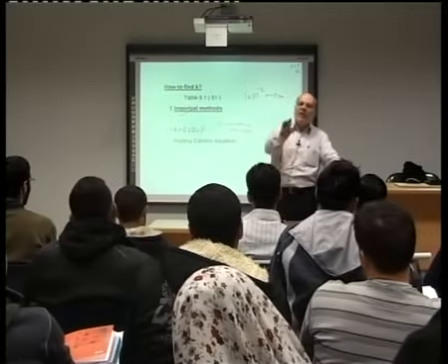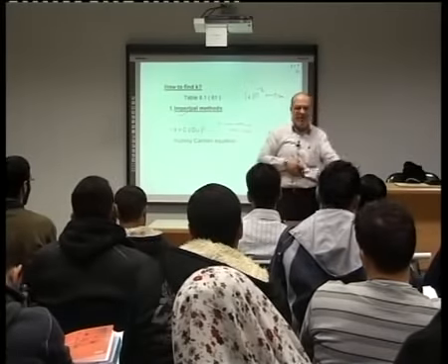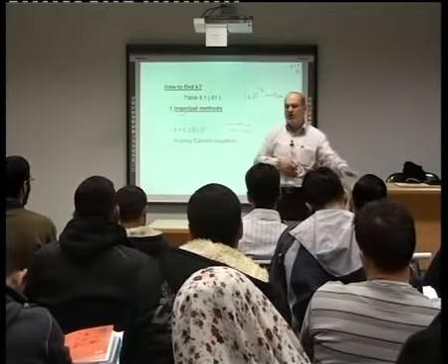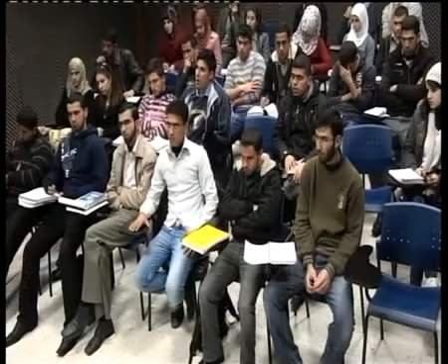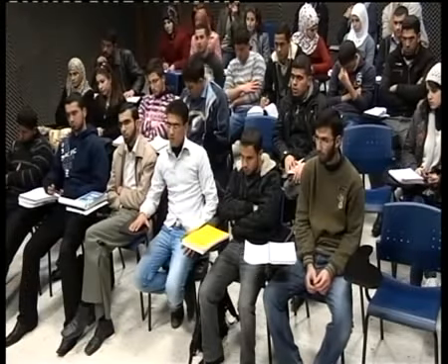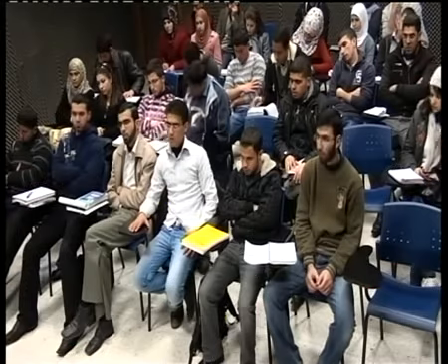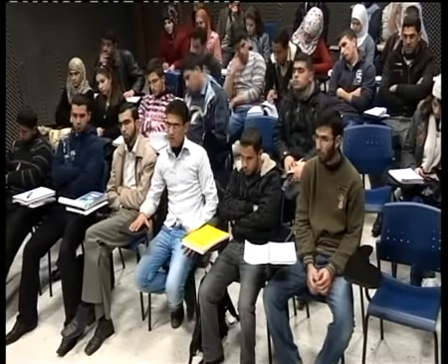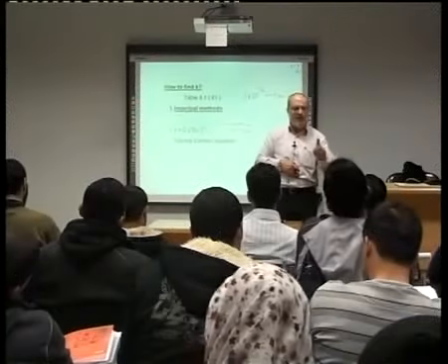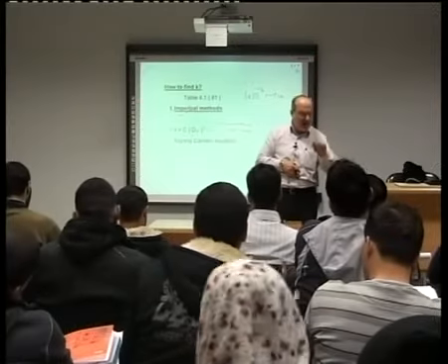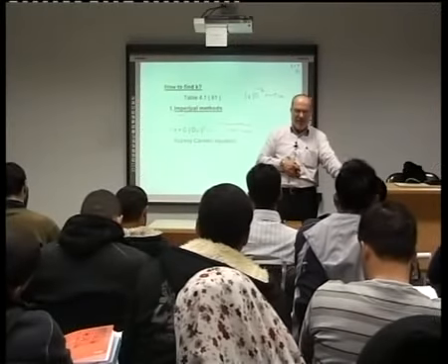okay? Can you apply this to something else? For example, if he was doing it on sand, can you apply it to clay? It's written that it's not applicable for clay, so you cannot use it. That's why don't use any equation, any relation before reading the assumptions and limitations of that equation, okay?